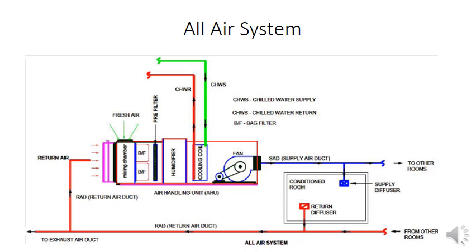Now this return air from the conditioned space is conveyed back to the plant, where it again undergoes the required processing, creating the controlled condition, and is again recirculated to the conditioned space, thus repeating the cycle. This duct carrying air from the space to the plant is called the return air duct.